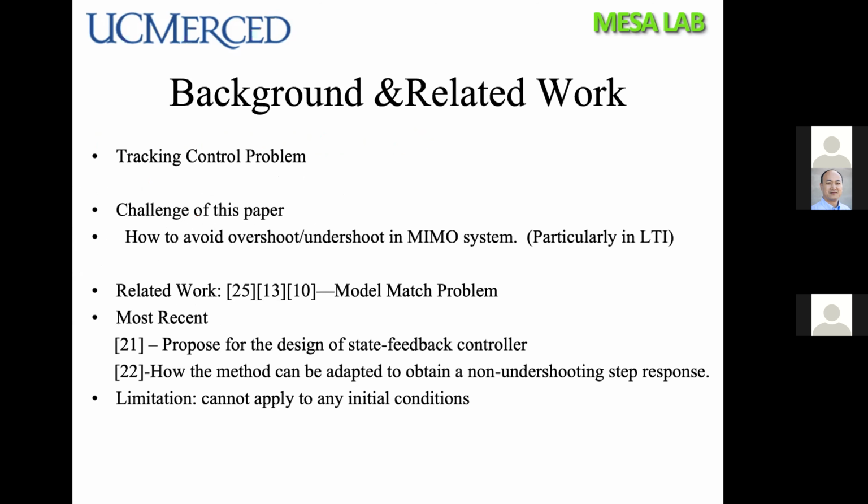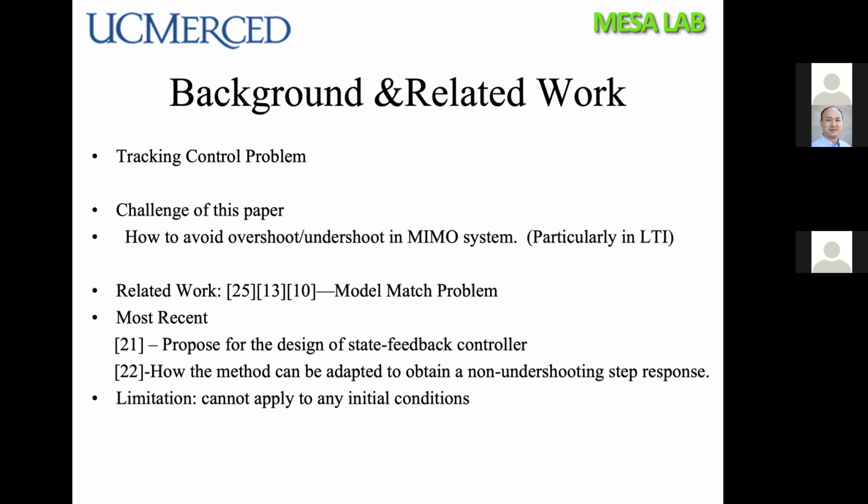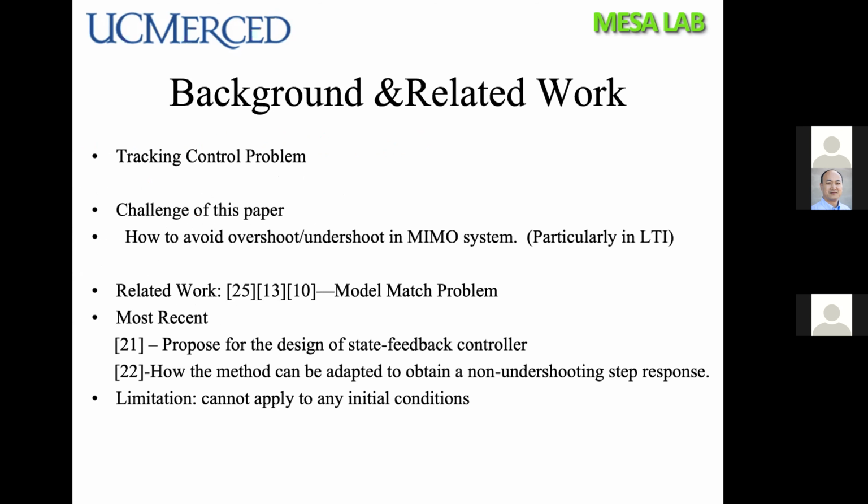So first things first, in this paper, I present a method for designing a linear time invariant state feedback controller to monotonically track a constant step reference at any desired rate of convergence for any initial condition. Necessary and sufficient constructive conditions are given to generate a monotonic step response from all initial conditions. This method is developed for multiple input and multiple output systems, and can be applied to square and non-square systems, strictly proper and non-strictly proper systems, and importantly, also minimum and non-minimum phase systems.